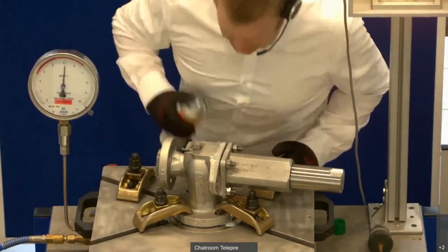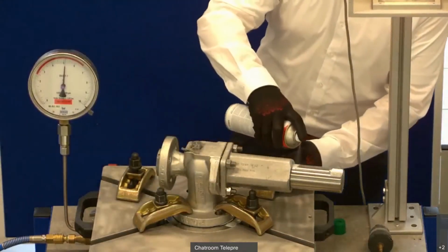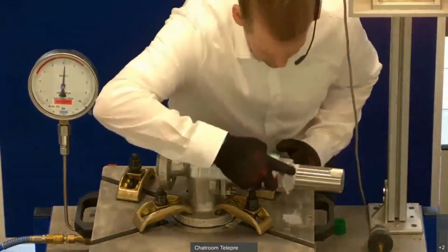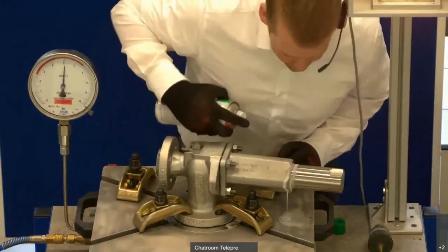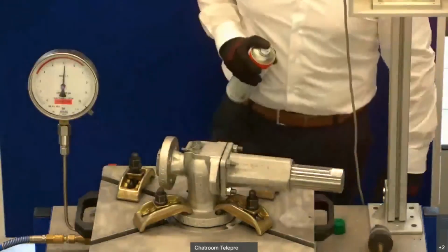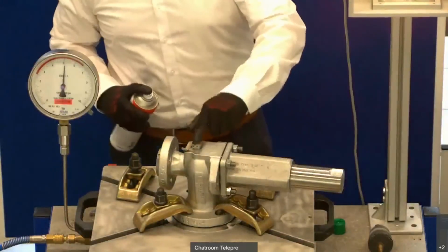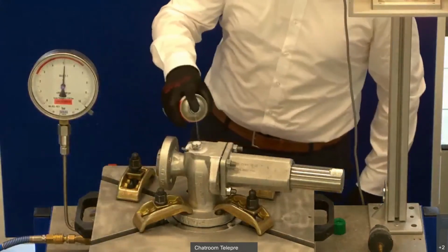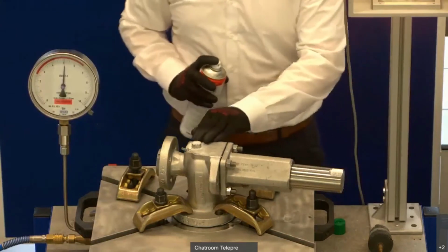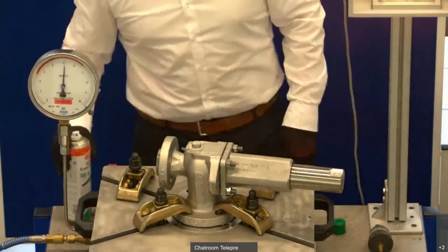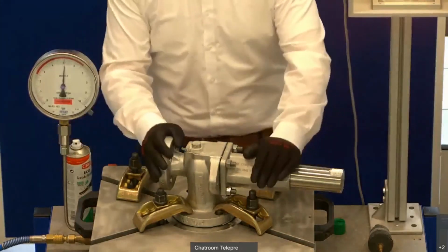Here we see no bubbles. Then the connection from the cap and the bonnet. You see again, no bubbles. And then have a look at the screw here again with some liquid spray, and there are no bubbles. And now the test of the body tightness is passed.